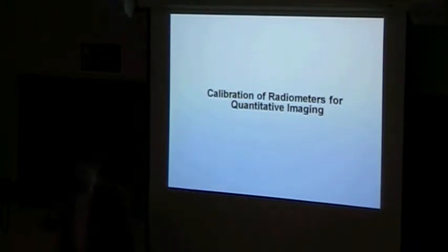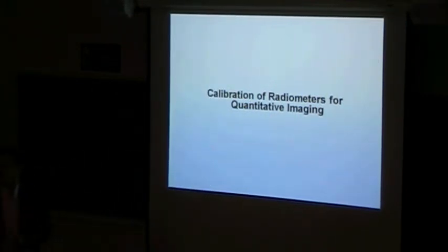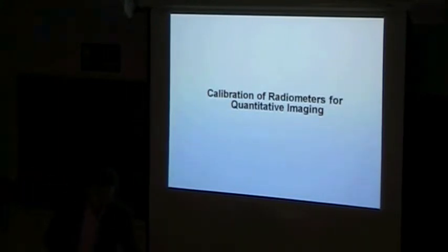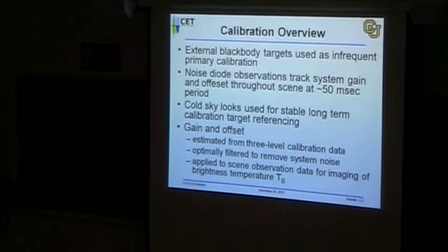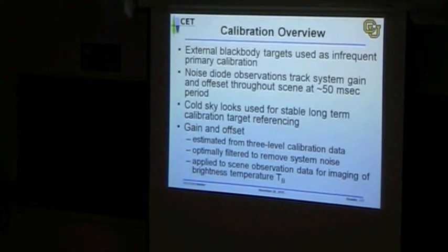Now before I talk about this holy grail a little bit more, I want to just point out what it takes to calibrate one of these instruments. Because unlike a lot of imaging applications, our needs are down at the roughly 1/2 Kelvin or better precision, given a total noise that is typically on the order of 500 or 600 Kelvin or higher. I want to put that in perspective for a moment, but it requires us to do a lot of rather careful work in taking these voltage measurements that come out of this instrument and then interpreting them as brightness temperatures.